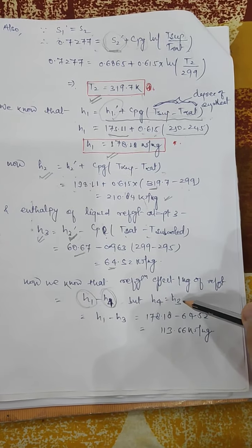Now we also know the formula for the volumetric efficiency, which is 1 plus C minus C P2 by P1. From Boyle's law, P and V are inversely proportional, so P2 by P1 can be written as V1 by V2. Putting the value C is 0.03 and the ratio of V1 by V2, the volumetric efficiency was calculated to be 87%.